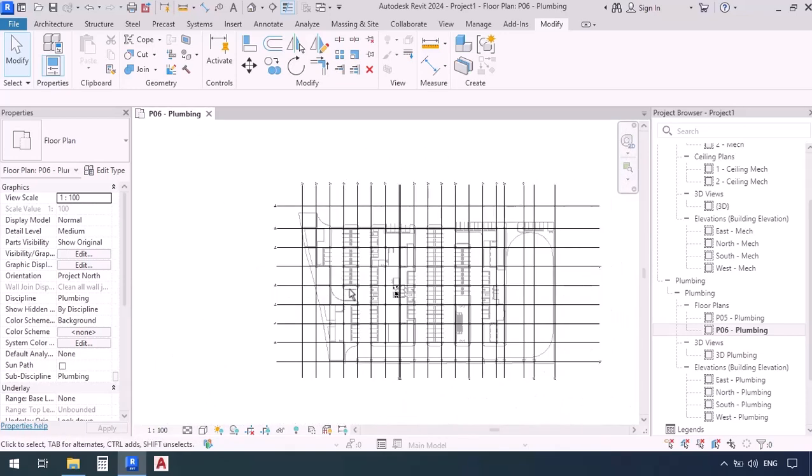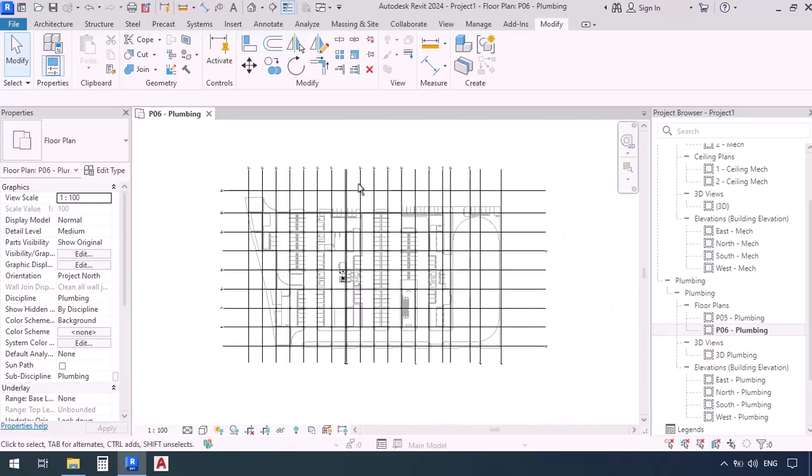First thing I should do with these grids is I'm going to have to take them from the architectural file and copy them into the structural plan. This is so that in case the architectural file got hidden, or for whatever reason we decide to completely remove it, then the structural plan would still have the ability to address things independently. So for that, we're going to try to copy these grids from the architectural file into the structural plan.